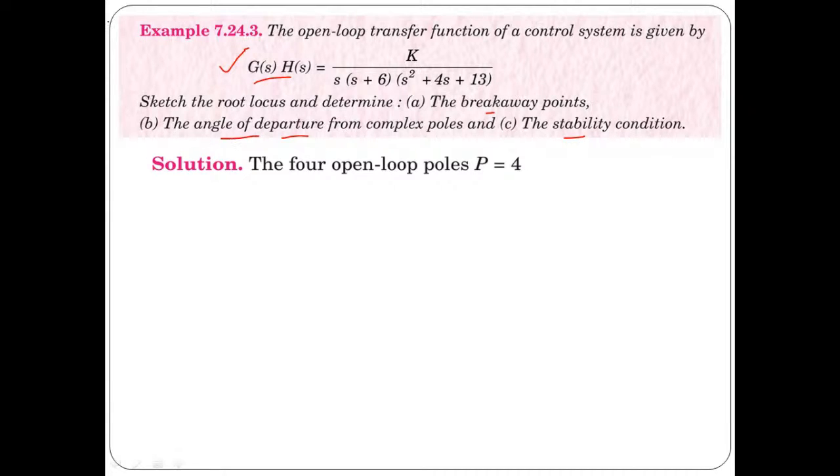So, as far as the root locus for this particular system is concerned, first of all, we need to obtain the open loop transfer function, which is directly given to us. Then we need to obtain how many poles and zeros are available in this system. So here we have 4 poles, and let us calculate the locations at which the poles are available.